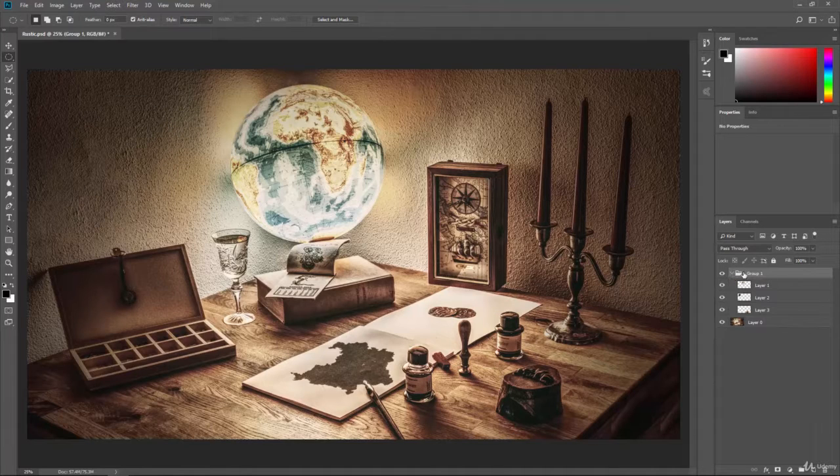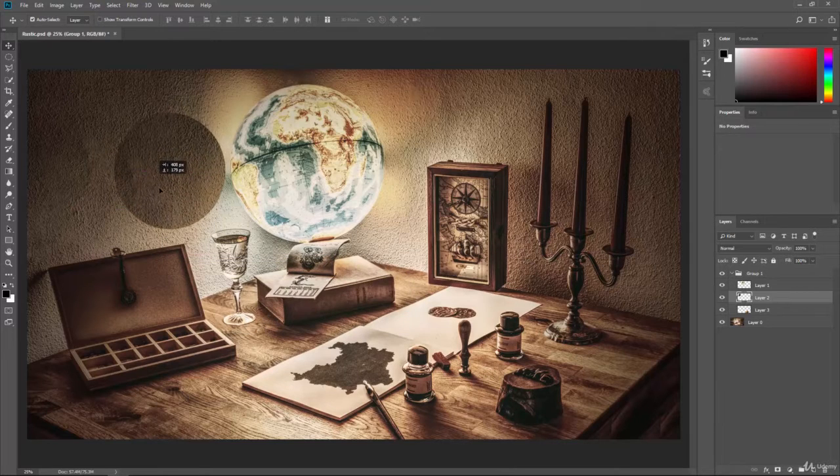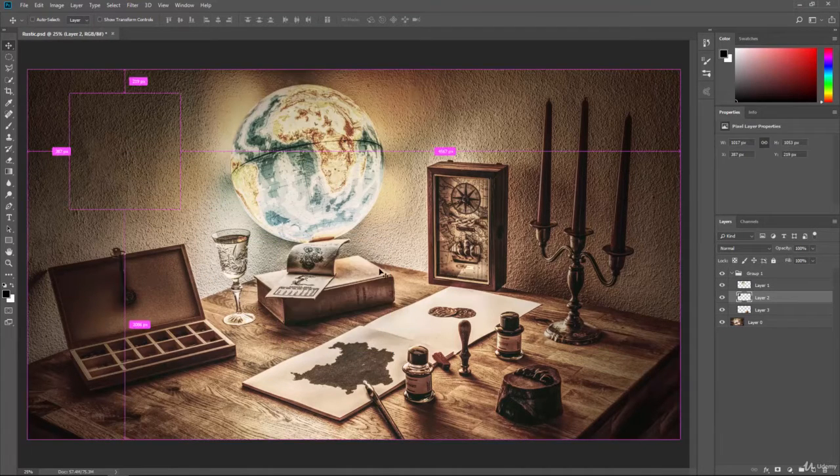group. And then what happens here is if I select that Move tool and I'm on the layer level and I grab the selection, it's going to grab the individual layer. Well, let's say that I want to move the whole group. So I'm going to select group. Now I'm going to grab that again and move, but once again, it selects just that layer. Well, we can move the group by changing this from layer to group.